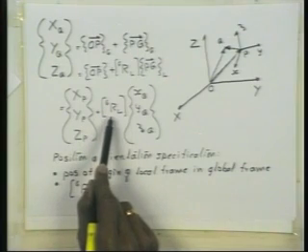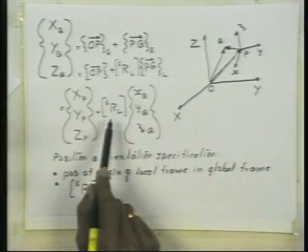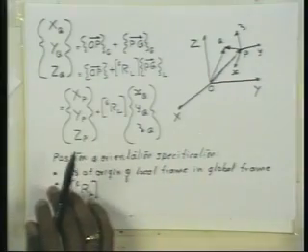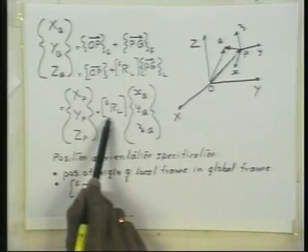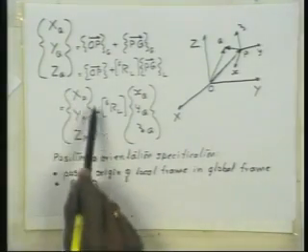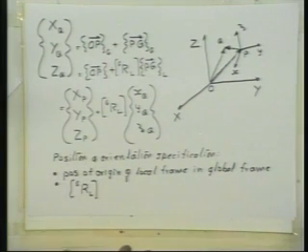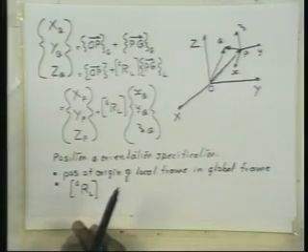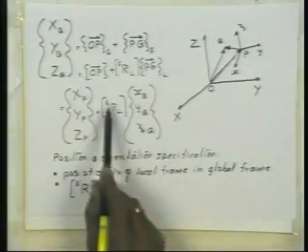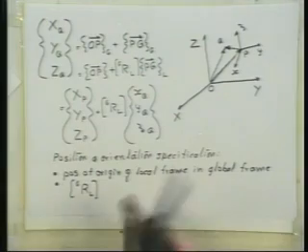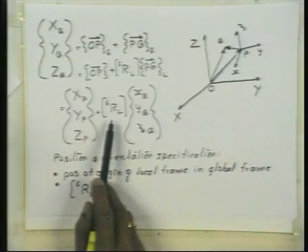Okay. Now look at this a little bit. Suppose I fix this. Imagine that the body is like this and the global frame is like this, and we have got these matrices and vectors. Now I am going to fix this, and then I am going to vary this vector, allow it to change. What happens to the body? It purely translates with the orientation which is already given to it by this particular specification fixed. Okay. What does it mean? It means that this particular matrix is able to fix the orientation.